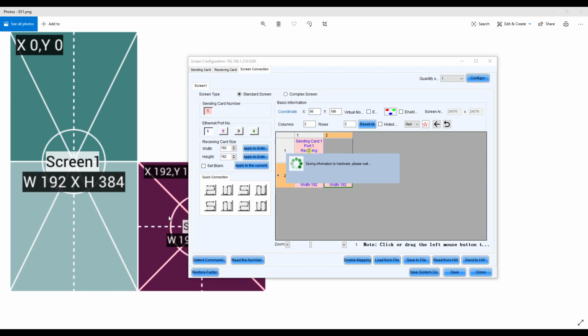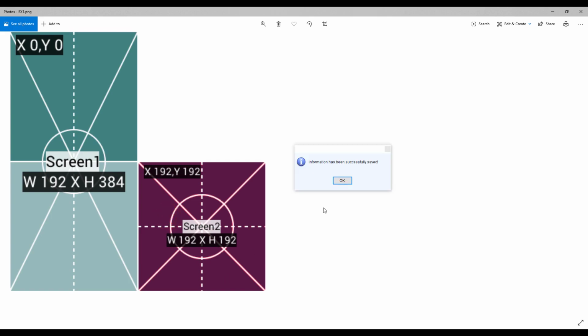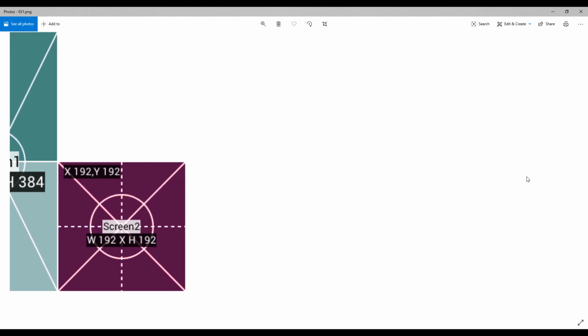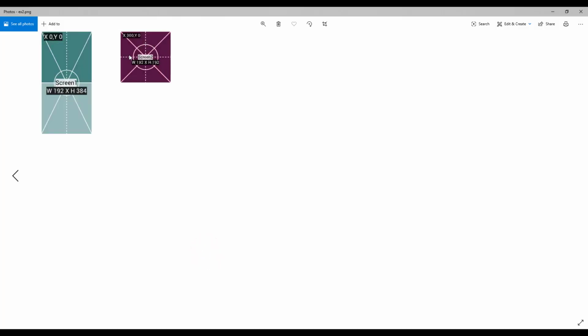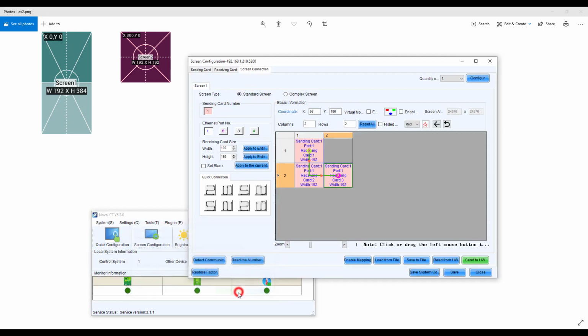But now what happens if you had to move this LED screen further out because your content is bleeding onto the screen too that's not supposed to be showing there? So then what you might want to do is, let's take a look at the second example of this. Right here. So if I wanted to displace the screen 2 to show this area of the screen without having to change anything, the better way to map this screen would be to separate out the 2 screens right here. Rather than doing 1 screen, do 2 screens.